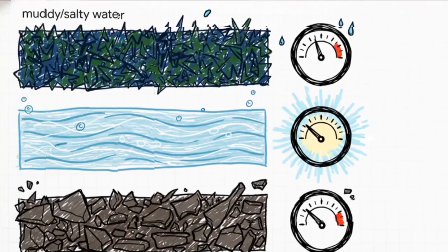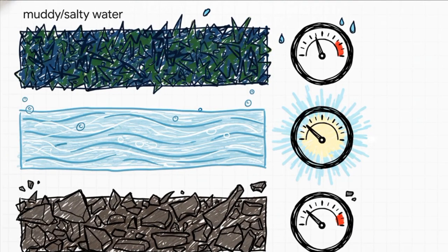So the crucial point here is that different materials beneath the Earth's surface react to electricity in super predictable ways. It practically acts as a subterranean decoder ring. If we're measuring less than 10 ohm meters, we're almost certainly dealing with clay or very salty water. If we measure somewhere between 10 and 500 ohm meters, bingo, we've hit the sweet spot. That's the typical range for an aquifer holding fresh, usable water. But if that number suddenly spikes over 1,000 ohm meters, well, we've hit solid, dry bedrock.